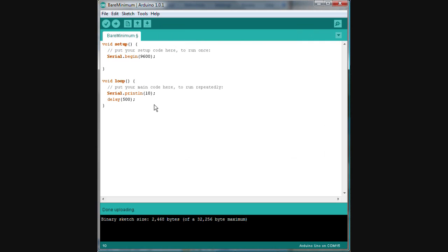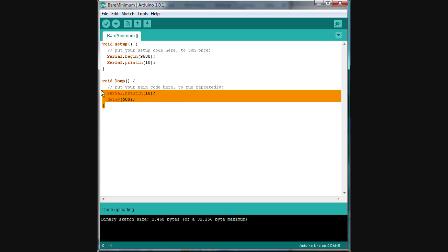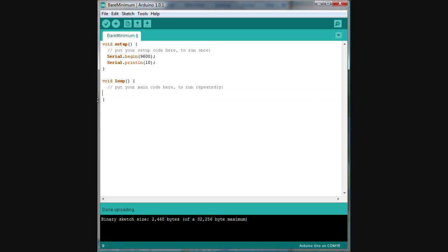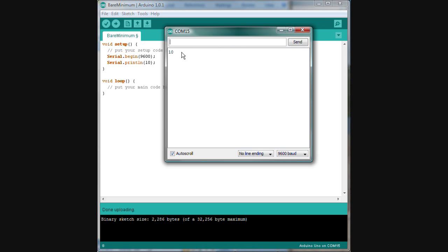So I have a brief little quiz for you. What would happen if we were to put the Serial.println up here in void setup? I'll give you a couple seconds to think about it. You can pause the video if you want. But if we were to do that, let's just take it here, we're going to copy it, and we'll paste it up here, and we'll delete this down in our loop code. And so now when we upload this, what you'll see is that it's actually only going to run once. So we'll see our 10, and then we won't see anything after that. So void loop will just sit down here doing nothing forever. Serial monitor, and there's our 10.